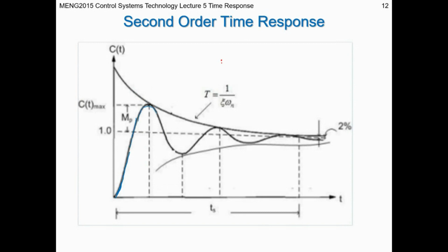So you can see it's got this sinusoidal shape, but the sinusoid is decaying or reducing in amplitude as time goes on, and it's decaying within a shrinking window. So you see there's a decreasing exponential here, there's also an increasing exponential here, and that basically creates a window within which your sinusoid is decaying.